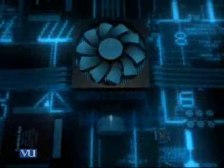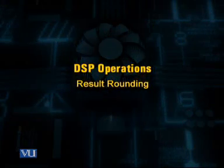Therefore, special care is to be taken to handle the results with overflow. And for this type of operation, the saturating add subtract instructions are available in the instruction set for the DSP operations. The next is the result rounding.